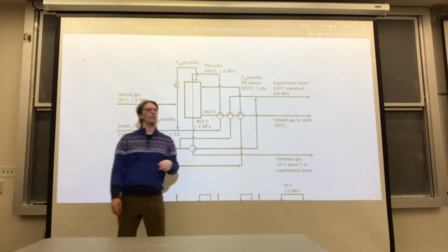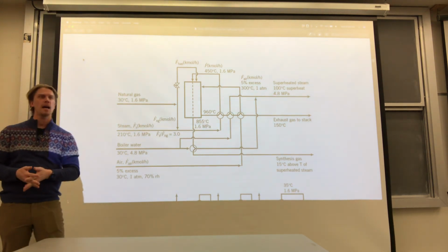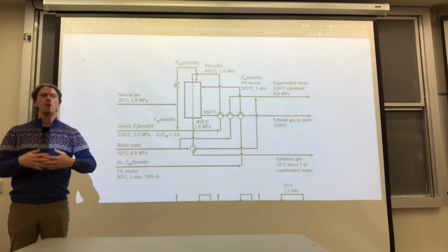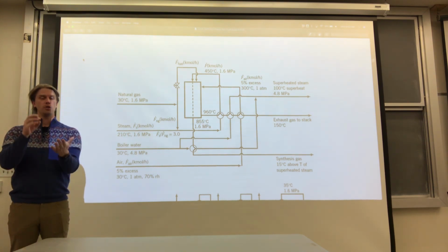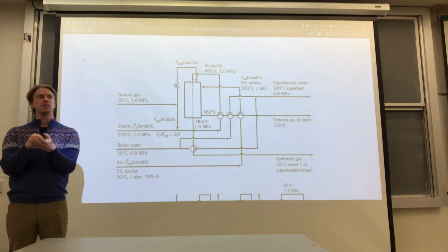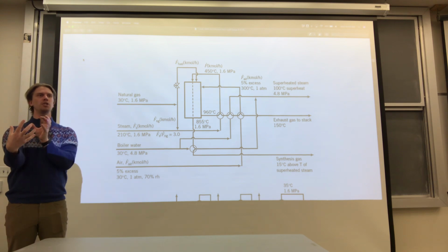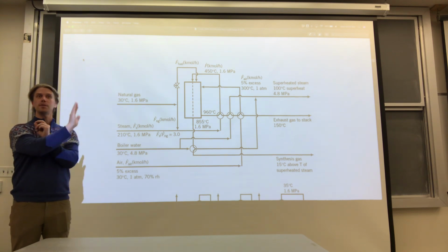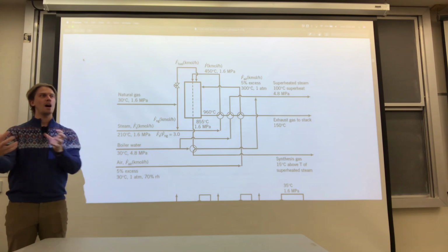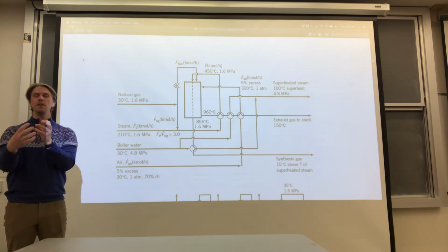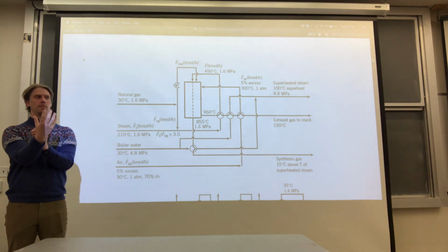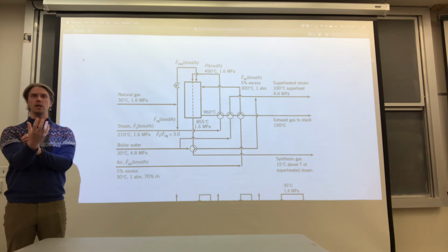Your heat transfer class will talk a lot more about how we actually design these processes. But in general, your furnace in your house has a heat exchanger. How your furnace works is you burn natural gas and air, and those exhaust gases shouldn't ever touch the air that's in your house. So you burn those inside a combustion chamber with a lot of conductive fins. The hot gases heat up the fins, and then you blow the air that circulates through your house over those fins. That's how the heat exchanger works in your house.